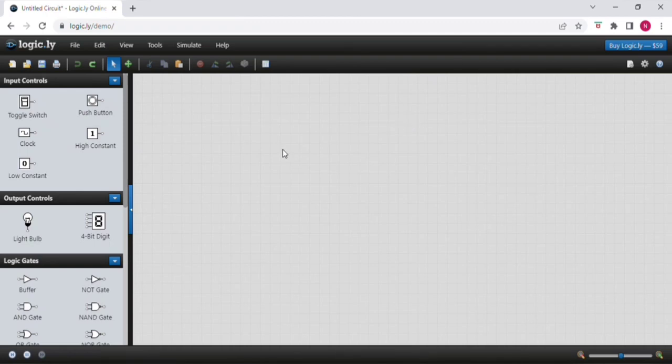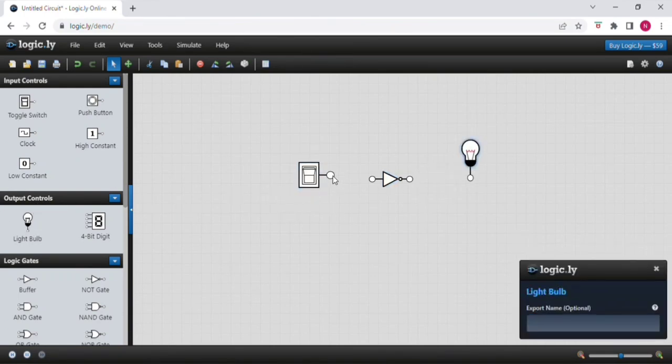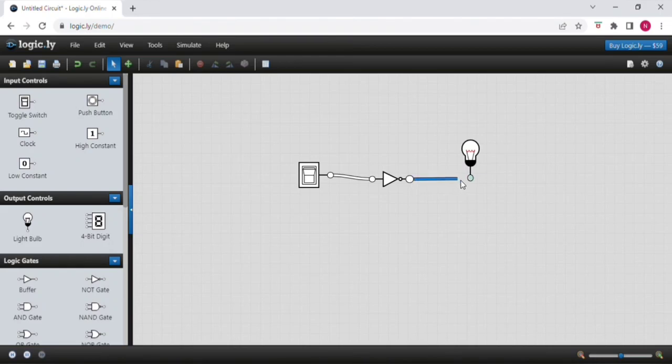So we can see the third gate, which is NOT gate. This is the symbol for NOT gate, where 1 is input and 2 is its output. We can connect the input and its output. This is the input and this is the output. We should connect each other. When the input is 0, the output will be 1, and when the input is 1, the output will be 0. This is for NOT gate.